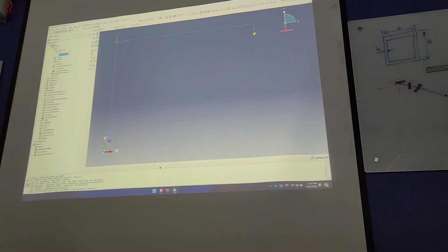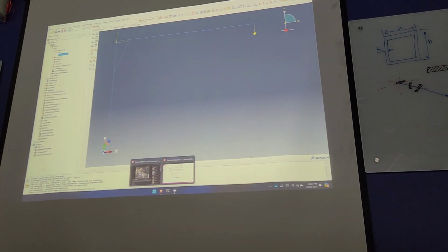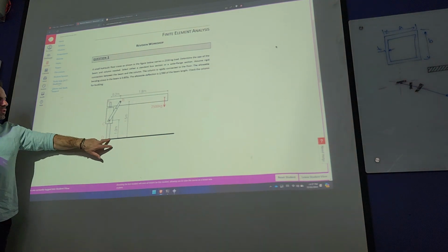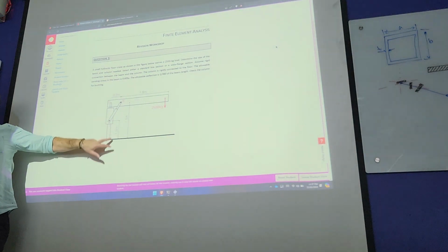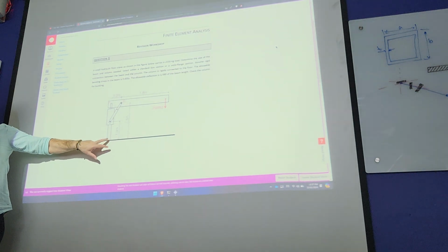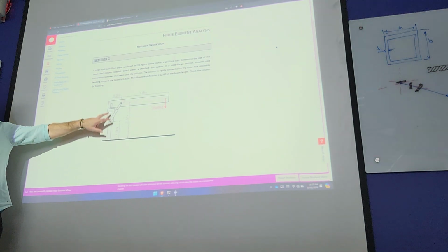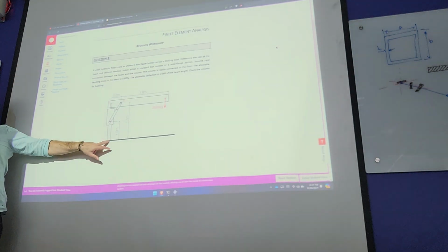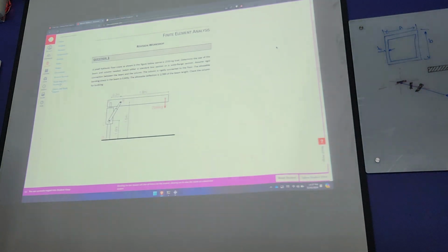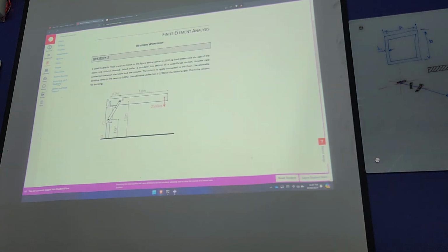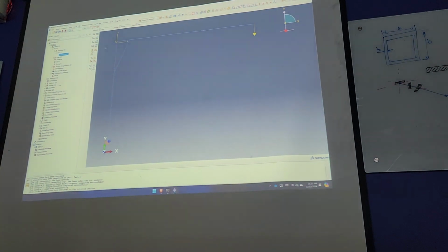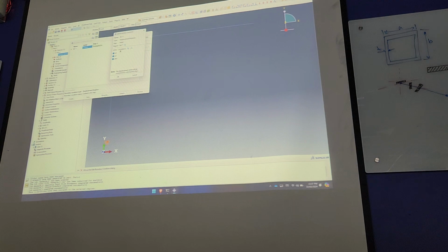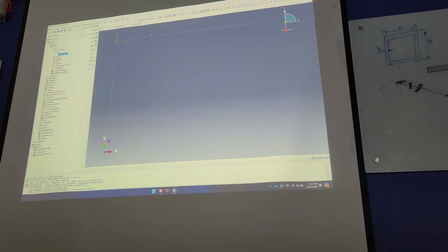Load, well, if you go back to this problem, there's only one boundary condition, which means that this vertical, the column, is encastred, so basically fully fixed at the bottom. It pivots around here, so basically locks in at the moment when it's loaded. So there's only one boundary condition here, yeah? So I've got encastre, sort of all degrees of freedom locked for that.